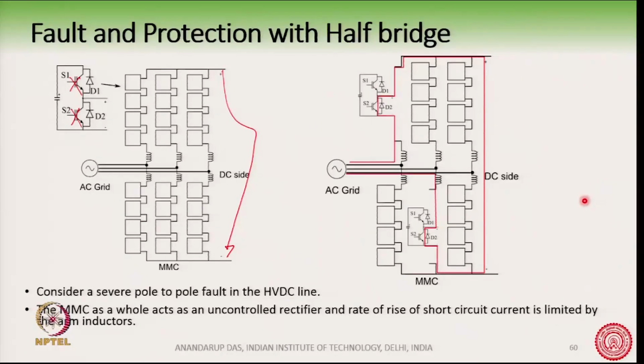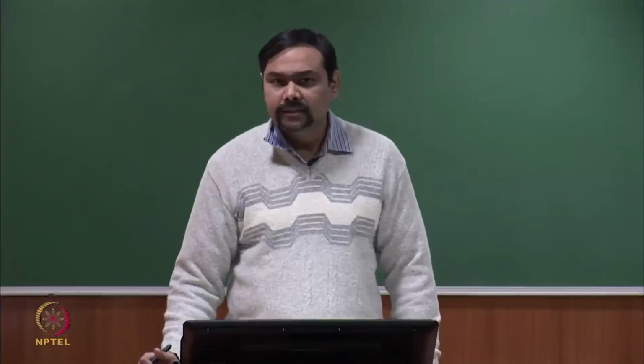And of course, the inductors should not saturate at that point of time, because during a short circuit condition the current through the inductor is going to be very high, and so the total MMF, or the total flux produced in the inductor, can be very high, n times I.